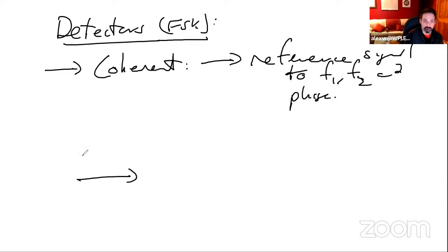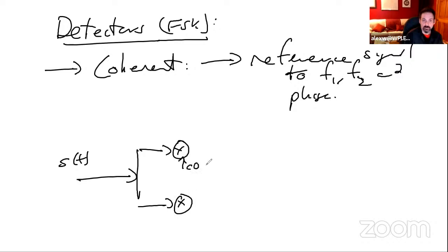So in came my passband signal. The first thing I would do is demodulate. So I would use cosine 2 pi f1 of t. And then I would just leave it at that. And here I would have cosine 2 pi f2 of t. You might say, okay, I could do that. Mind you,